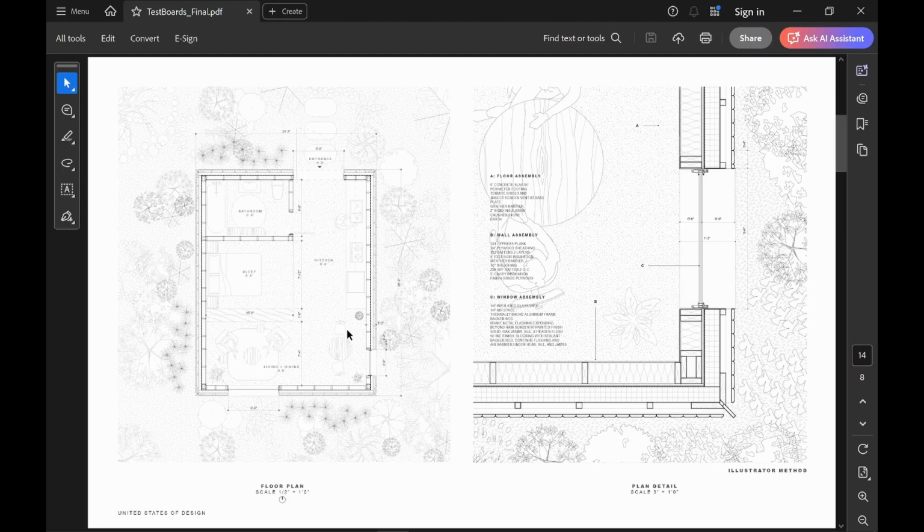So what we could have done is when we did this plan in Illustrator, we could have taken it and just scaled it up by 100 or 200%. Like we could have scaled up like 300% to get this. That's the nice thing about Illustrator. So let's say you worked on a floor plan and you made it very detailed in Illustrator. Instead of redoing all of the line weights again, you can just scale everything up and make sure that when you scale things up, you have scale stroke and effects as well. And then you might have to readjust some of the line weights. But that's the biggest pro of Illustrator, is that you don't have to do the work twice.